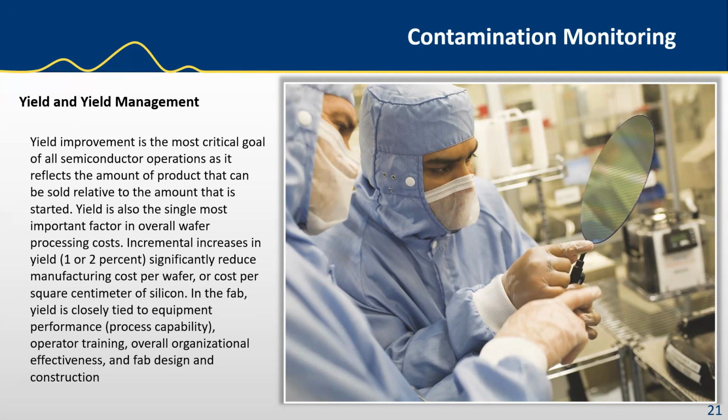So continuous device miniaturization in the semiconductor industry and the trend to go larger and larger with die sizes means that particulate contamination has an ever-increasing impact on yields. Today, over 80% of yield losses of VLSI chips manufactured in volume can be attributed to random defects in contamination.